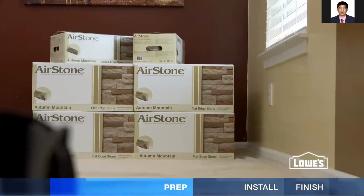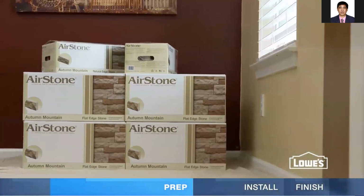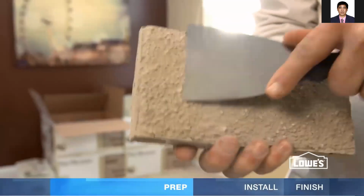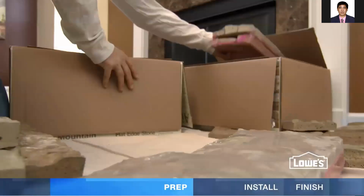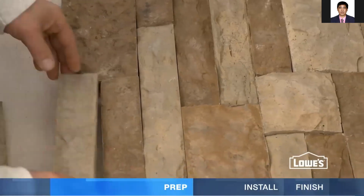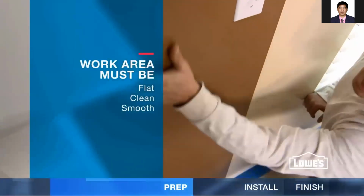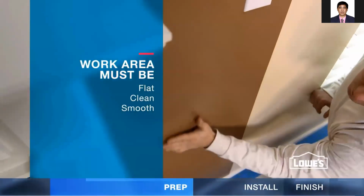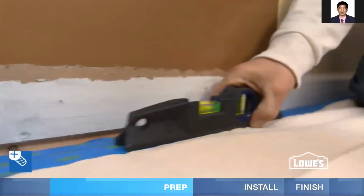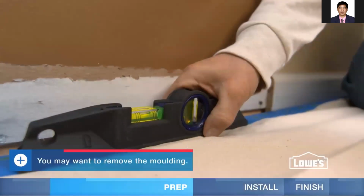Let the stones and adhesive acclimate in the room for 24 hours. This is a good time to remove any bumps or nubs on the stones and to plan your layout. Mix stones from different boxes and alternate sizes to break up vertical seams. As for your work area, it must be flat, clean, and smooth. Lightly sand surfaces painted with oil-based paints. Also check that the floor, countertop, or molding is level.